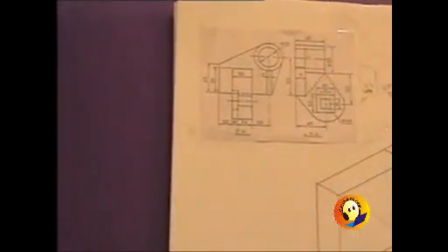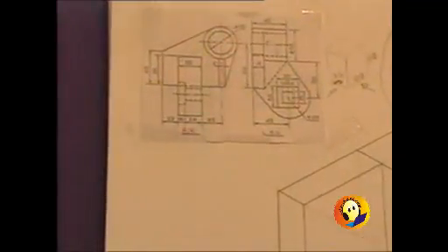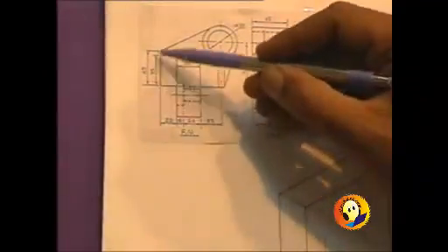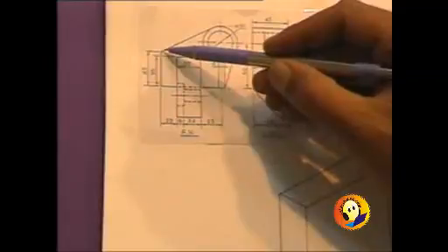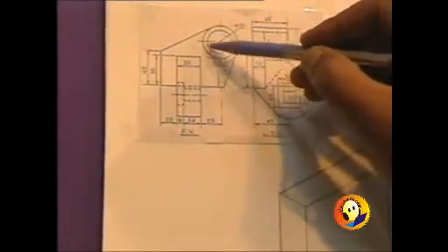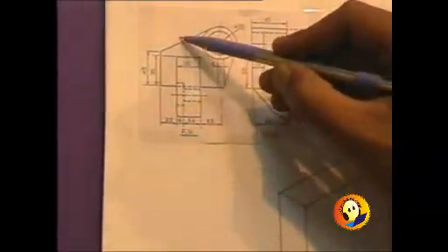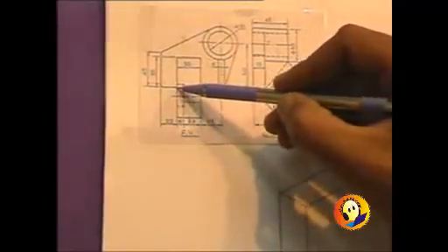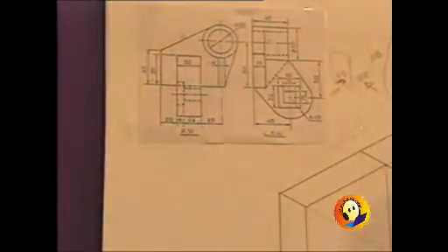You can see most of the distances. Now this height was given to us as 45, so the plate can be made dark up to height 45, and from there it is inclined. The back line also can be drawn, but unless we draw the circle, you cannot draw this line because it is tangential. So we cannot draw this line first of all. We can start with this plate. We can draw this line, 20 mm, which is visible. There is an intersection. You can see the imagined figure.